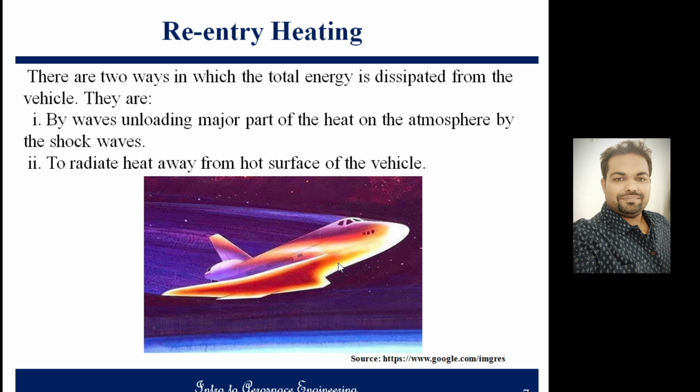So usually for the spacecraft, we make the nose a blunt nose, right, to avoid the formation of an attached shock. If there is no attached shock, there will be no large aerodynamic heating. To avoid the large aerodynamic heating, it is a bluff body, right? A bluff nose. In that case, the shock will form at a distance away from it. In that case, the surface of the vehicle will be subjected to less heating.